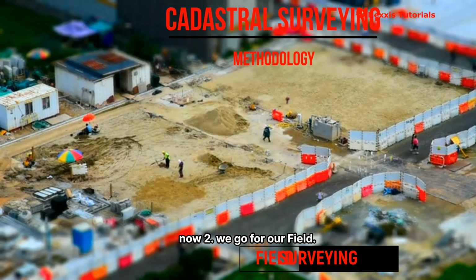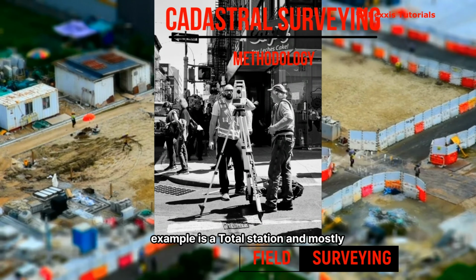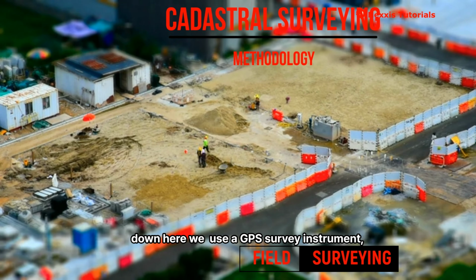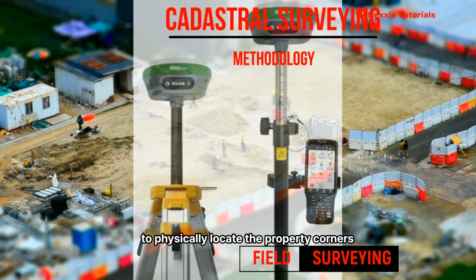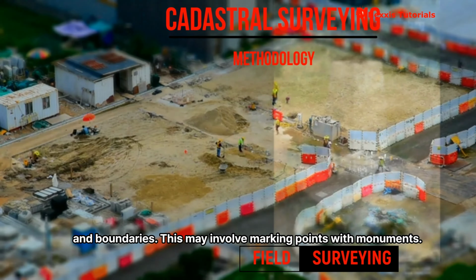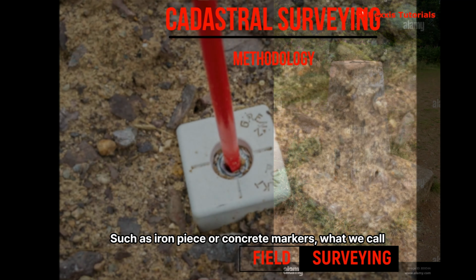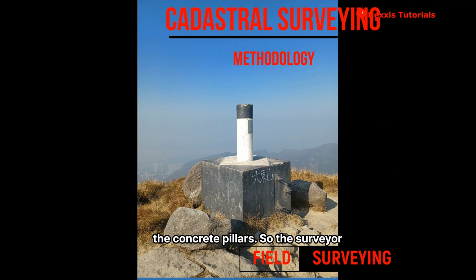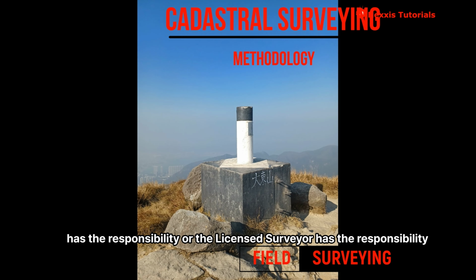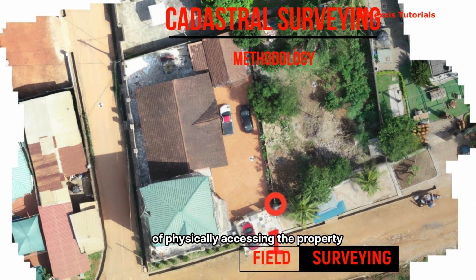Now 2, we go for our field surveying. This involves using specialized instruments. An example is a total station, and mostly down here we use a GPS survey instrument to physically locate the property corners and boundaries. This may involve marking points with monuments such as iron pins or concrete markers, or what we call the concrete pillars.